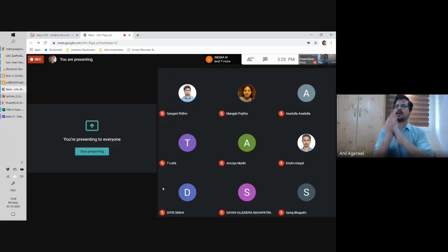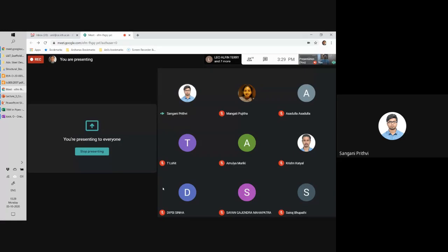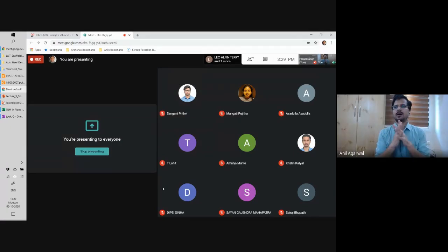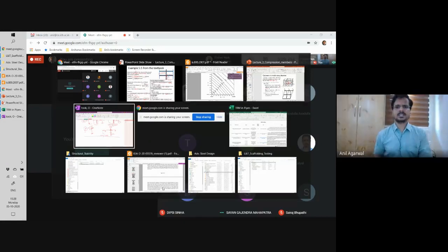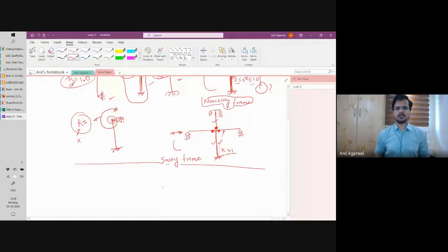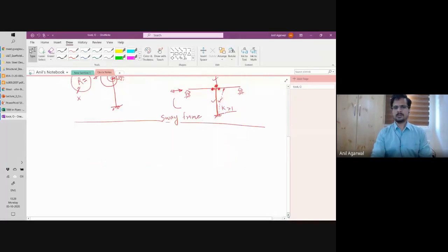So they usually avoid that. So in the minor axis, most of the time you will not have a rigid frame. You will have a rigid frame only in the strong axis. So the beams and columns will be oriented in such a way that you have a rigid frame only in the strong axis. Yes, sir. Does that answer your question? Maybe I can quickly draw something also. It's an interesting point, and it comes from design practices more than the fundamental concepts.